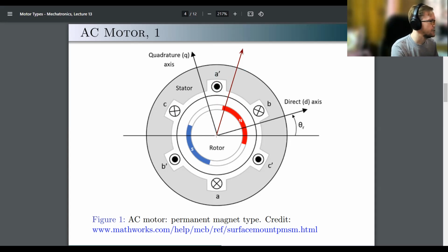This means that our North Pole, and here I'm sort of simplifying again, I'm using this idea that your magnet will orient itself along the magnetic field. So your North Pole would want to rotate this way, right? Let's say we rotate it, and our motor now faces something like this, right? It rotated a little bit. By the time it rotated a little bit, your total magnetic field will be facing this direction,